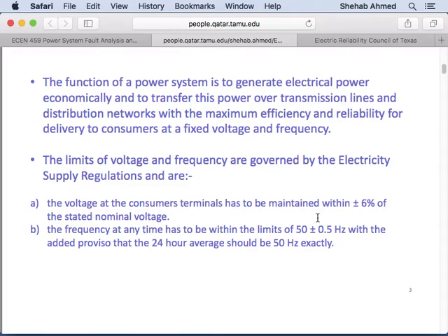And maybe if you do the optimization process, you will find that beyond 500 hertz or 1 kilohertz, the benefit you gain in size is not too much anymore versus the amount of complexity that you have to add in the electronics, right? So airplane power systems operate at 400 hertz mainly because of weight.